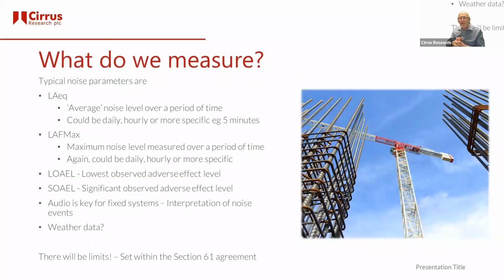I say semi-fixed because obviously construction sites develop, and where the noise might be coming out of one boundary is really bad at the moment, in 2 or 3 months' time, because of where the construction works have gone, the noisiest areas might be somewhere else. So you may need to move your monitors at some point in the future.